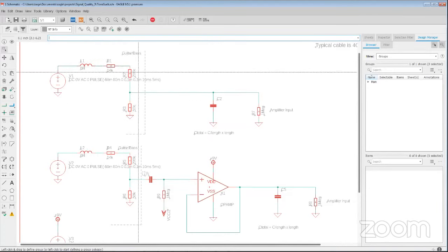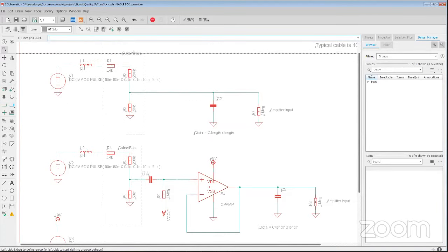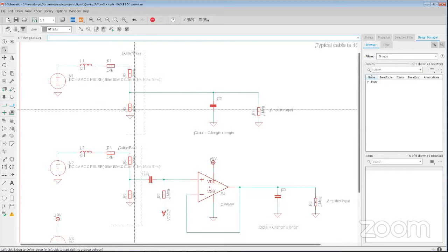Now, up here, we've modeled a passive instrument. This type of instrument doesn't use a battery, doesn't have any type of active amplification, and it's also not buffered. So its impedance is going to be mostly dictated by whatever the volume pot is. And that's what these two resistances here are representing. This is basically a 250 kilo ohm volume pot. So the lower the resistance feeding this line, the less deterioration we have arriving at the amplifier input.